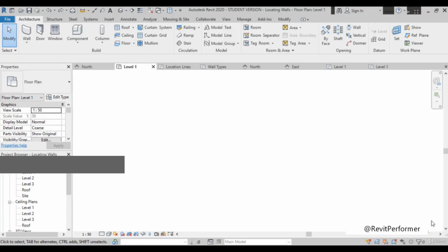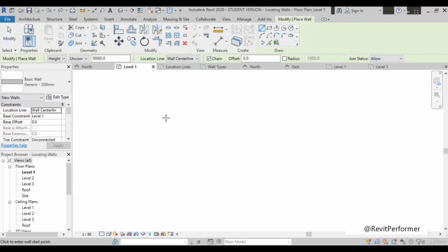This is the technique that we use in this lecture, which is very interesting. Some of the previous movies will talk about that. Meanwhile, it is often good to go into Revit by first laying out geometry in a rough location. So let me start. Go to the Architecture tab, go to the Wall tab, take a wall.